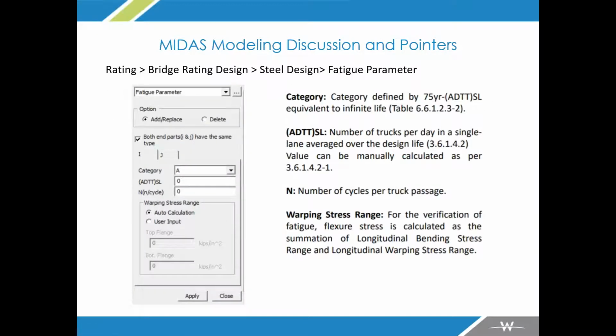As far as the rating goes here, you can set your other parameters. If you want to look at fatigue, you can look at fatigue. A lot of times we're mainly looking at the inventory and operating, not as worried about fatigue as far as load rating because the loads are unusual. Particularly your permit vehicles, you're not getting enough of those for fatigue to usually be an issue, but you can also incorporate it if you so choose.